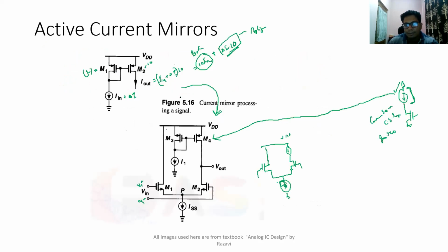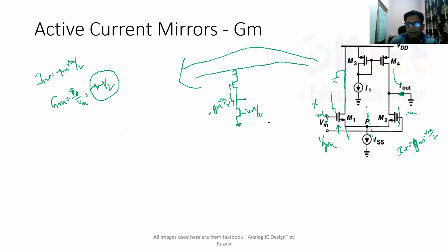The problem with this circuitry was that on one side only you have the load; the other side you don't have a load. So in the analysis we did here, I only took this side of the circuit and ignored this side, because its current was simply doing nothing. It was just going to ground. Instead of wasting this current, if we can utilize it for amplification purposes, then we may get a good amplification and end up with what is called a differential amplifier.